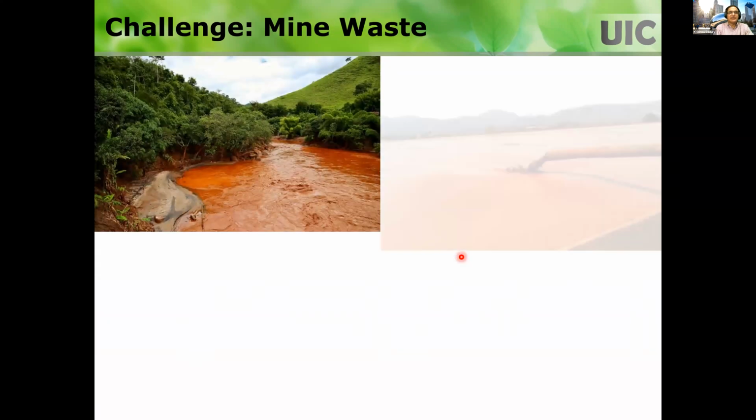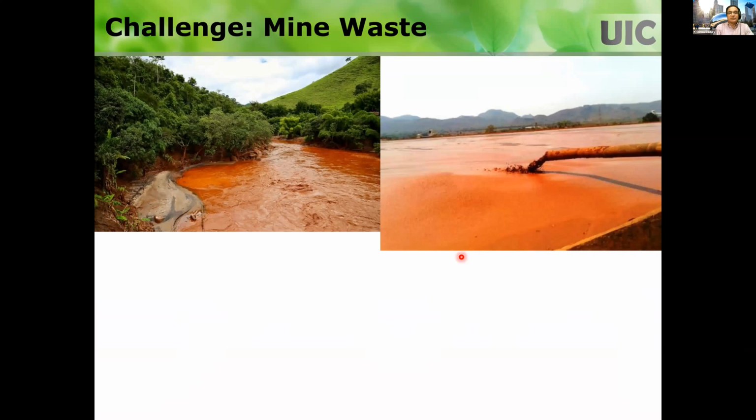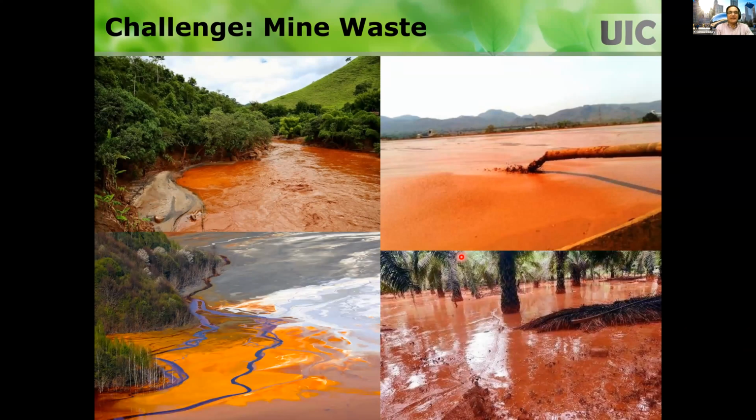And mine waste. There are so many mines in India and all over the world, and some of the mine waste is not environmentally friendly. It could be highly alkaline or highly acidic. It could have a lot of contaminants. So you need to ensure that these facilities are physically stable. Not only that, the contents must be contained. If you have releases, a large area is going to be contaminated, and cleaning that up is very difficult. So you're going to affect the people, you affect the land. You're going to have a lot of issues with these kinds of things.